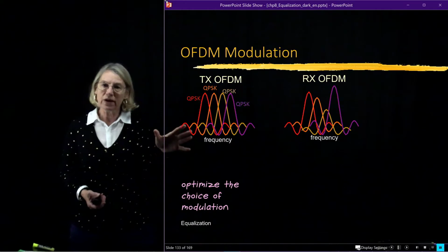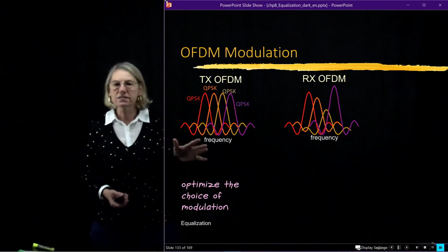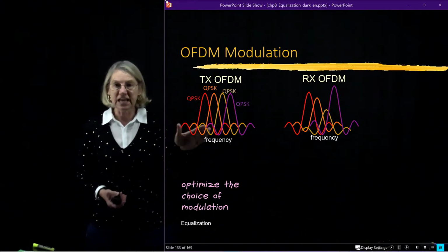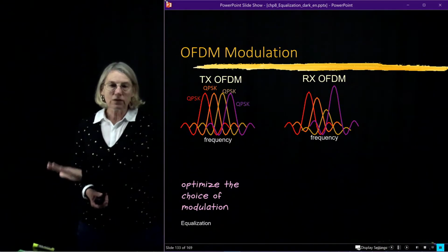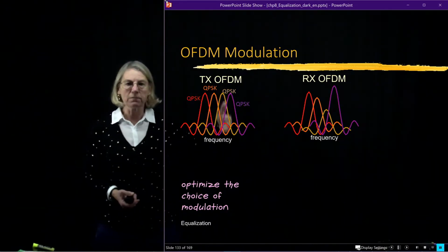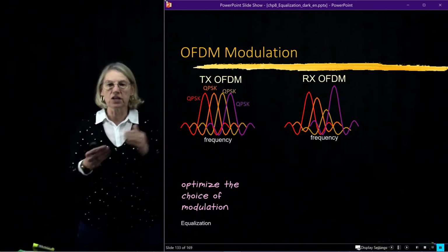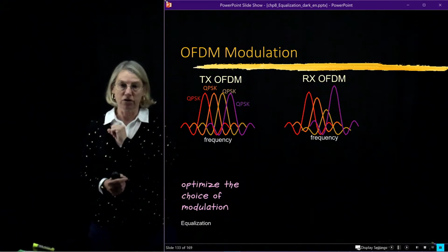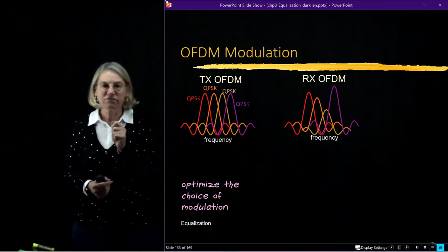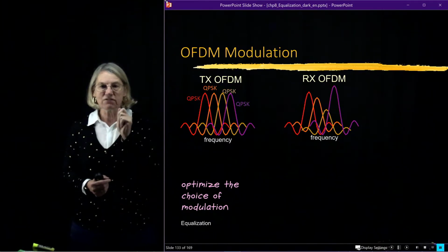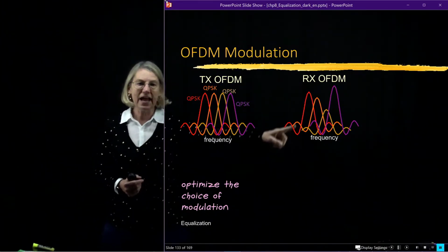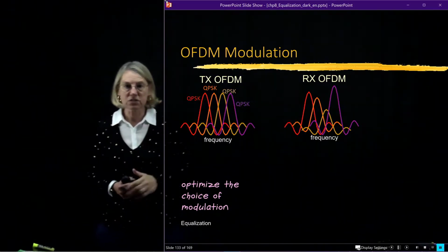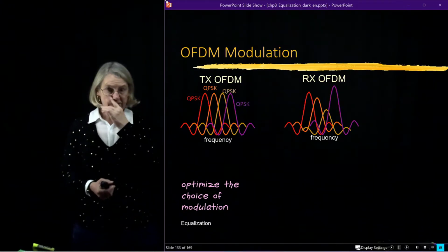In fact, what I want to try and do now is not just be robust to the impairments of the channel. Remember, the strategy of going with OFDM was to avoid equalization, because in each one of the parallel ones I didn't really need equalization because their multipath effect was counteracted. But maybe I could go farther. Maybe it's not just a question of avoiding equalization, avoiding intersymbol interference. Maybe I can actually do another kind of level of equalization, if you will, by taking into account what's going on in the channel.